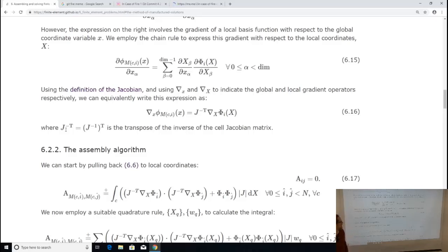So minus t, if you haven't bumped into it before, is a conventional notation for take the inverse and take the transpose, or vice versa, because they commute. And that J is the cell Jacobian that we already worked out how to do. Right? The cell Jacobian is d little x, d big X. This one is d big X, d little x, and it just so works out that if you have a Jacobian and you dot product it onto the right-hand side, you end up contracting out over what's on the bottom of the Jacobian, and that's not what we want.